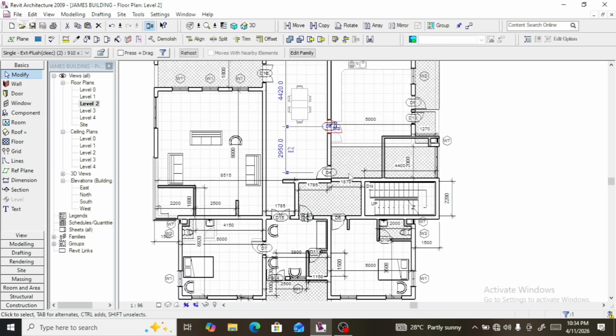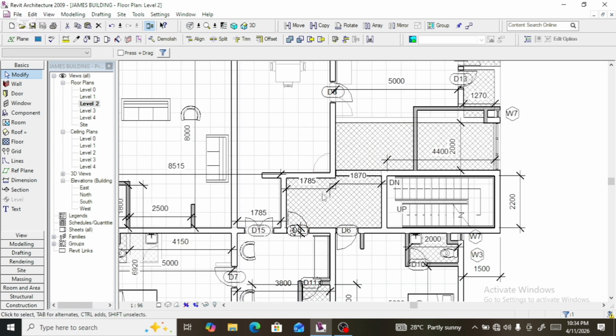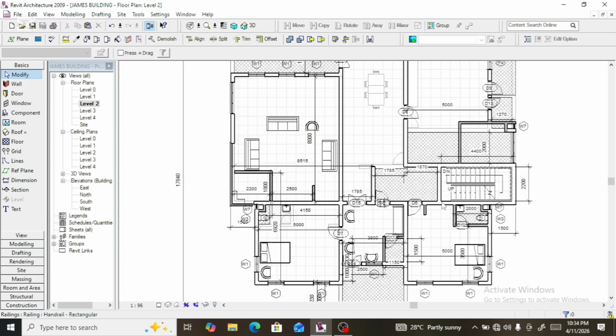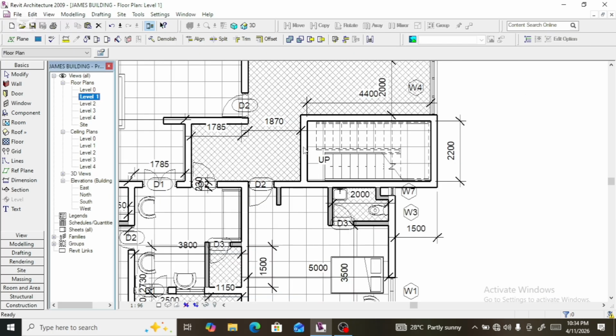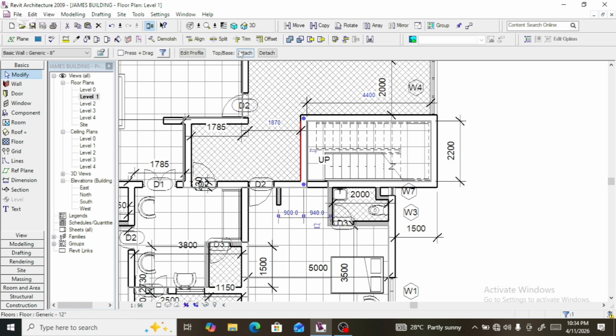Okay. This is out. This wall is going out. So let's trim to extend these two walls together. So remember, this wall is coming this way. There's something we never did at the DPC level. At the foundation, we did not cut this wall. It's an error. It came upstairs like that.